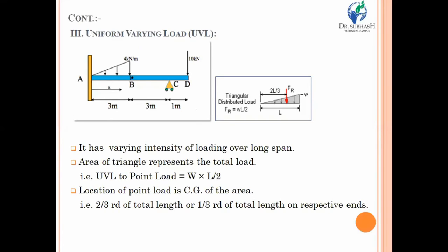There is a beam A, B, C, and D. Section wise, if we are talking, section AB is subjected to some triangular type of load. Actually, it is a symbolic form of uniform varying load. Its name gives that such type of load has a variation of intensity from one section to other sections. For example, over here, the intensity of that particular load is 0.